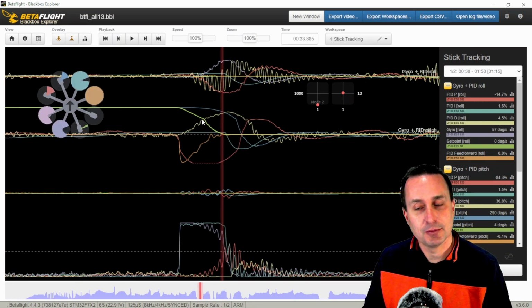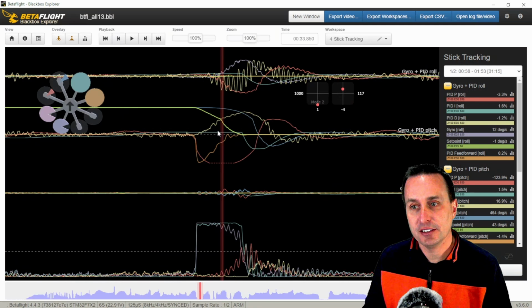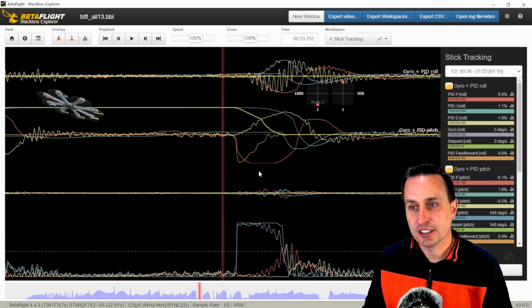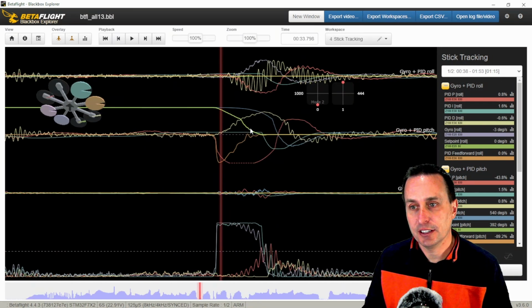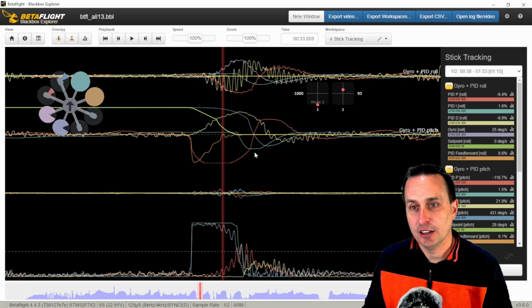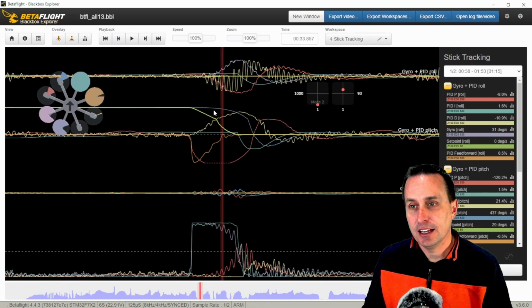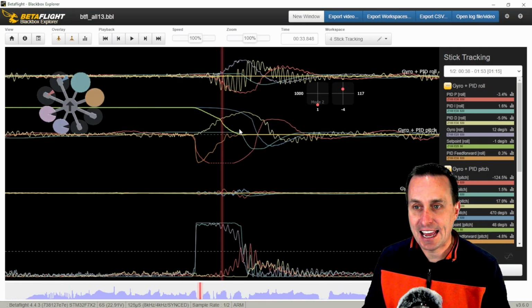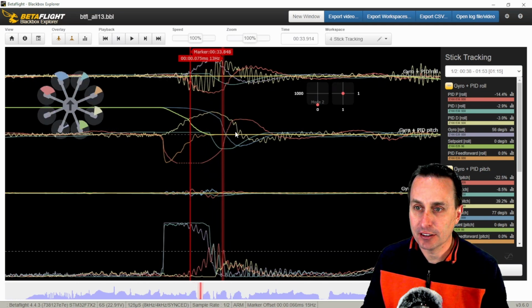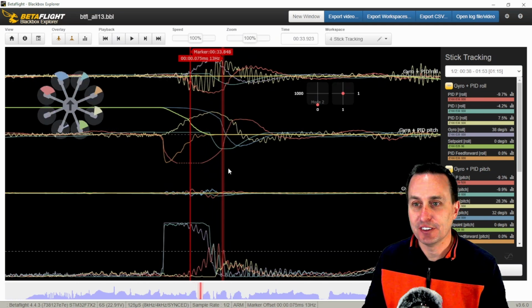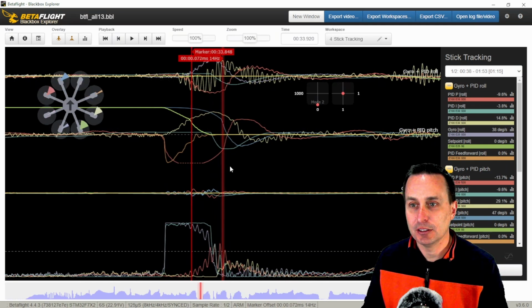You can see right here, this is the gyro. Or I'm sorry, this is the sticks. This is the commands. And you can see pitch axis right here, going down to 0 right there. So it's a forward flip and going back to 0. And then this is the actual quad. Look how much gap that is. That gap between there and there, just quickly eyeballing, it's like 75 milliseconds. Maybe a little less, something like 70 milliseconds.